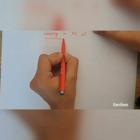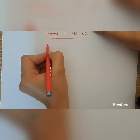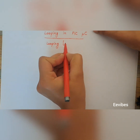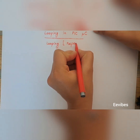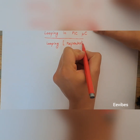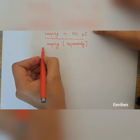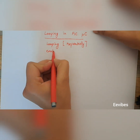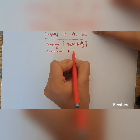I will explain how you can perform looping in the PIC microcontroller. And before starting that, I will explain what is meant by looping. By looping we mean if we want to perform some tasks repeatedly, then we use the concept of looping in programming. Fine, and for performing the looping we have conditional branches or unconditional branches.